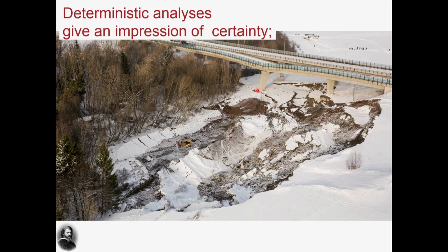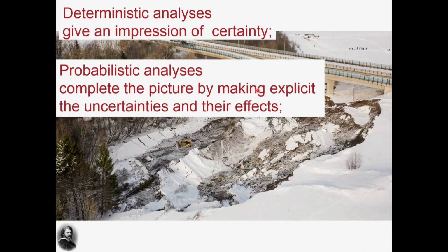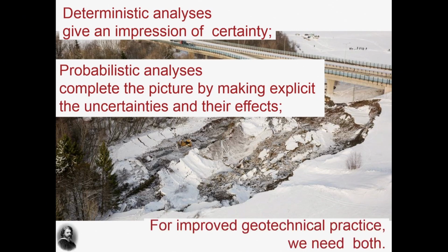Deterministic analysis gave an impression of certainty. People say, factor of safety 1.5, oh, that's good. It's never going to fail. Probabilistic analysis completes the picture by making explicit the uncertainties and their effects. And for improved geotechnical practice, we need both.